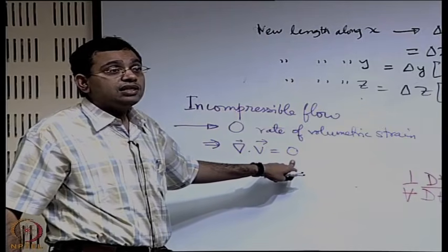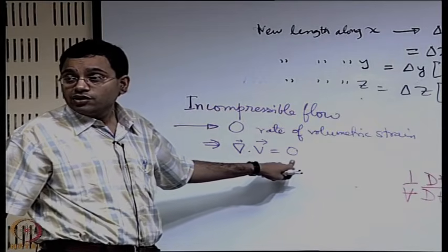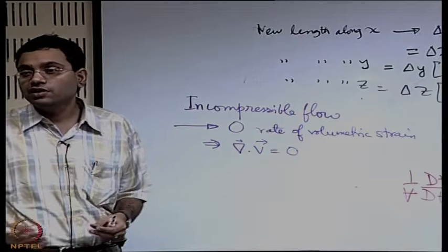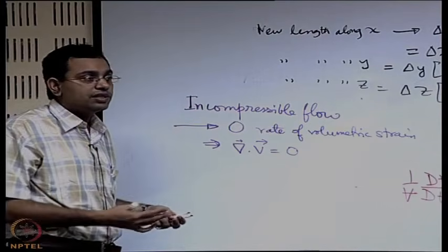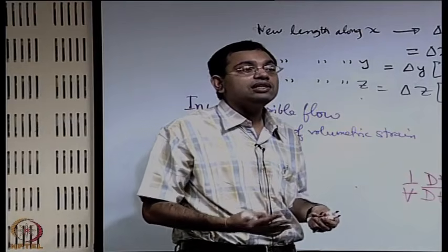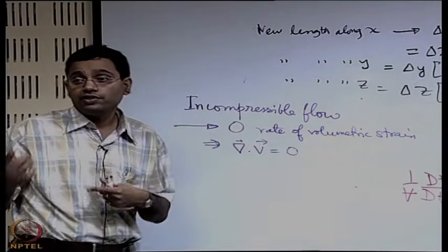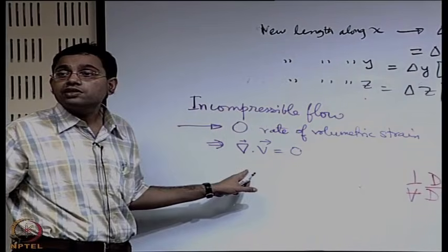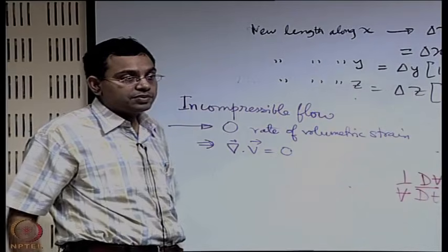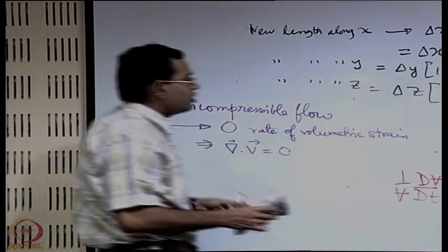Keep in mind the distinction between this definition and the incompressible fluid definition. So earlier we also introduced the concept of incompressible fluid, and we said that a fluid is incompressible if its density does not significantly change with change in pressure. So that is incompressible fluid. Now we are talking about incompressible flow, and these two are again related but different concepts that we have to keep in mind.